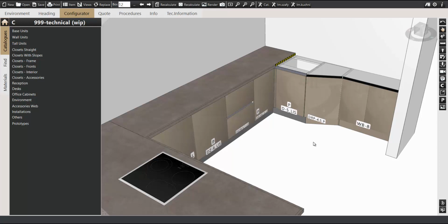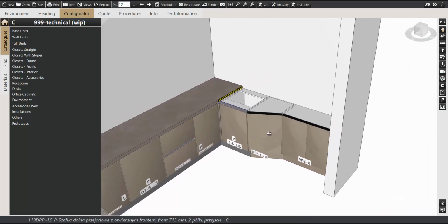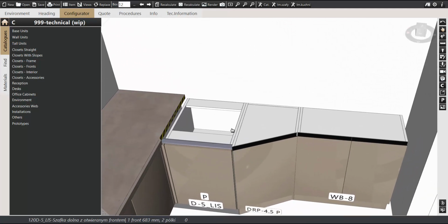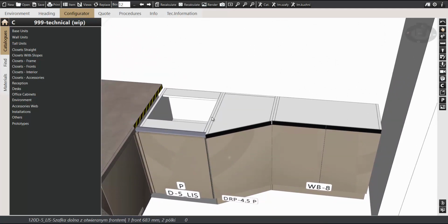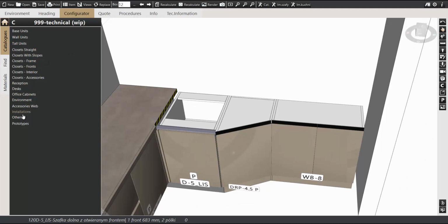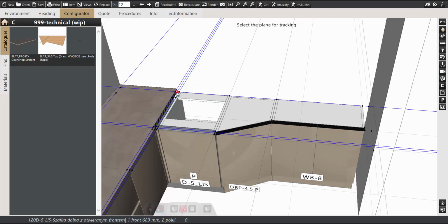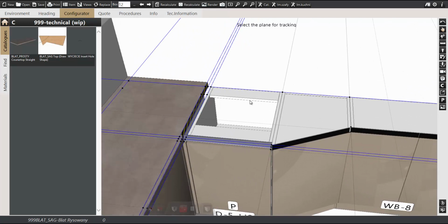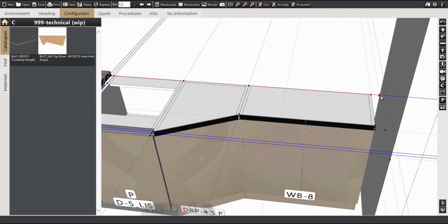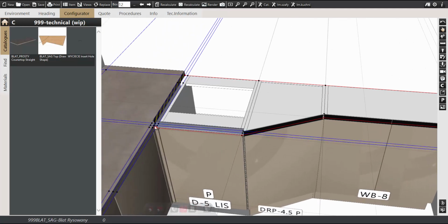A lot of customers ask how to construct a countertop because, especially for kitchen, it is a really special topic. So we explain it in two examples: one in an existing construction, and another one on how to handle individual plates that are not generated directly by the item. There is a lot of possibility, like this tool where you can place a countertop. Naturally, you need to fix a little the points where it is connected. Don't care, it is not important to have all the direct points like height in the beginning. You just finish with the first points to define the contour of your countertop.